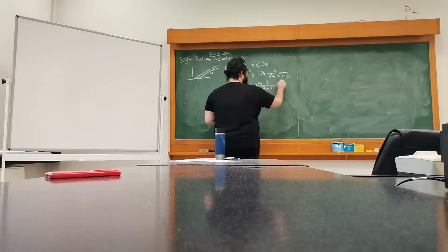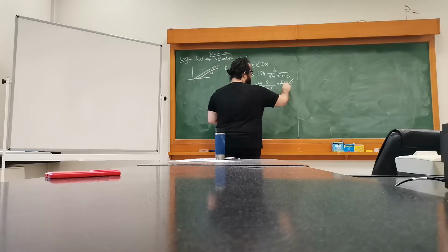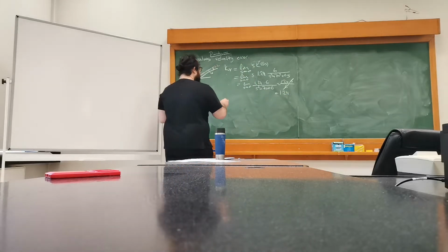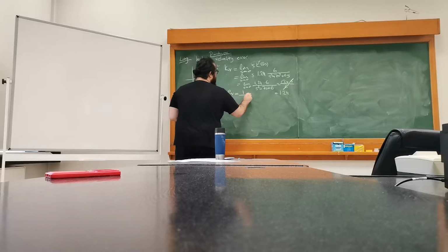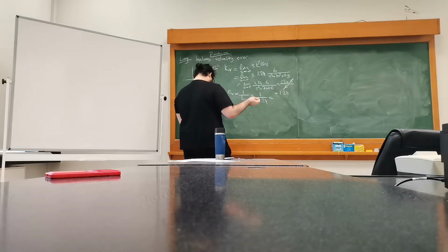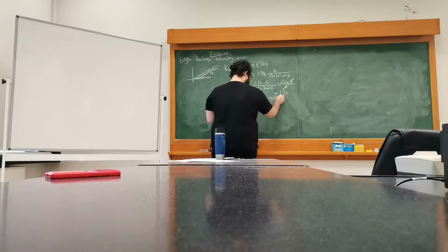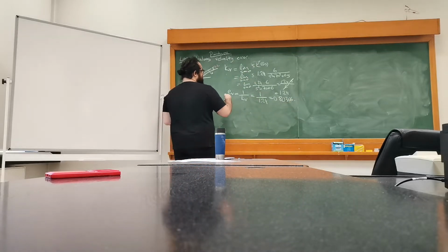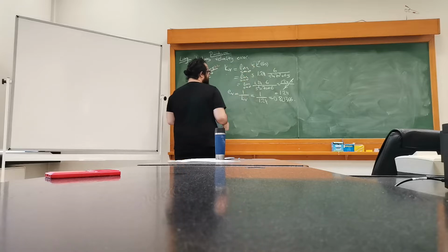And this is basically 1.24 times 6 divided by 6, 1.24, or the P-type controller itself, basically. And the velocity error here becomes 1 divided by Kv. Therefore, this is 1 divided by 1.24, or the P-type controller. That gives us 0.80366, etc.